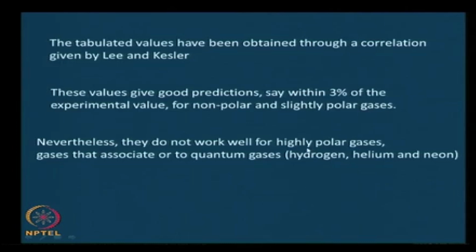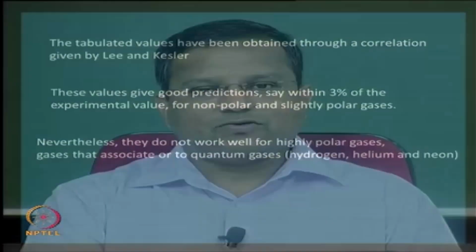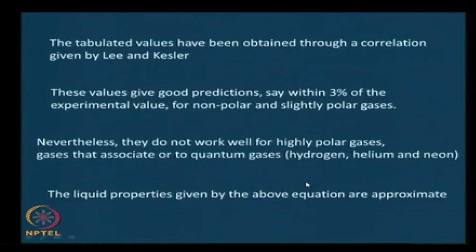They do not work for the highly polar gases, and gases that associate or quantum gases also do not work very well. So, we need to be a little careful when we apply the generalized equation of state to these gases: highly polar gases, gases that associate, or quantum gases. Further, you can use this equation when you are considering the liquid state, but the accuracy of the values is not very high.